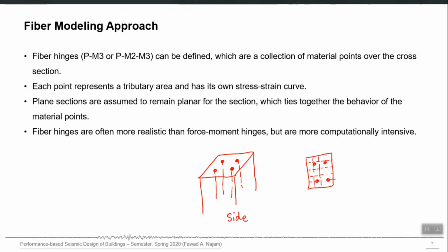So I cut that cross section into a certain number of sub elements. Each sub element, let's say this one which I am shading, now runs along the whole length of the column. Actually it may run along the whole length or up to a certain part of the length, we will decide that later. Similarly, this is one rebar, and it is also running along the length of that element.